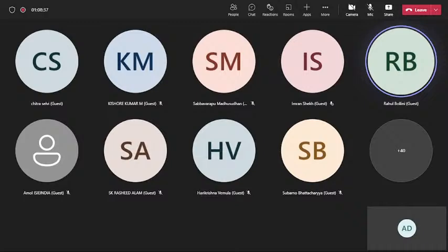So when you take it out, you can actually reuse it, but it has to be slowly charged and slowly discharged. So it goes for solar applications. See, the Indian market is very young, so probably you will not see all these things because batteries age over 3 to 5 years and then it comes. And most of them are using low quality cells or used cells coming from China. That's what is happening in Indian practices.